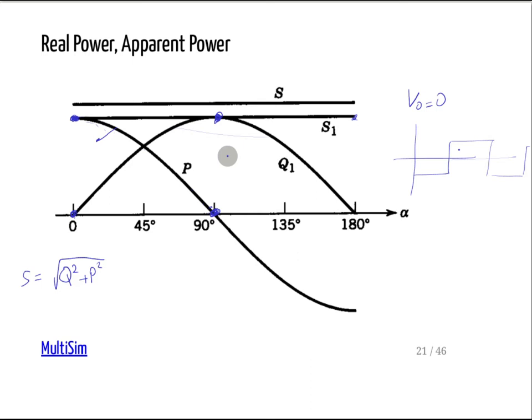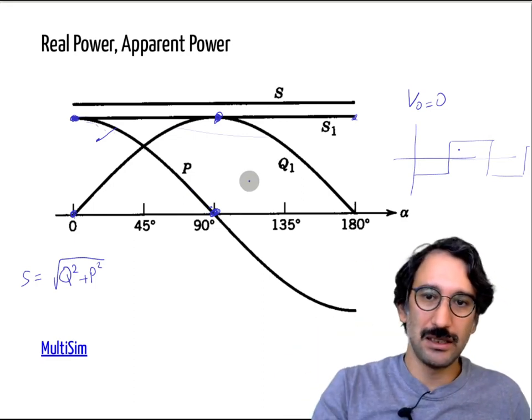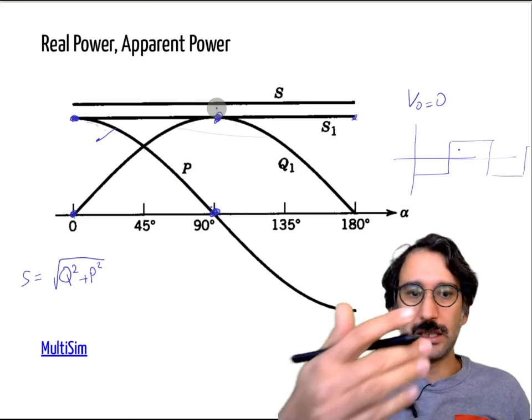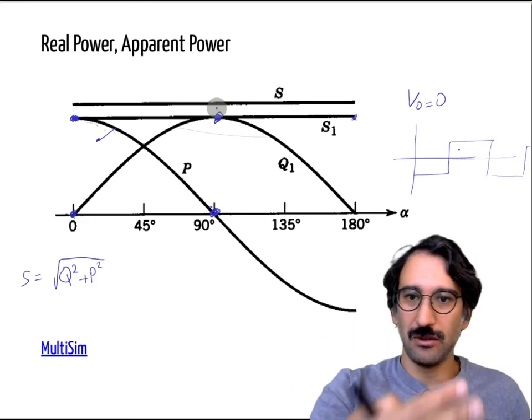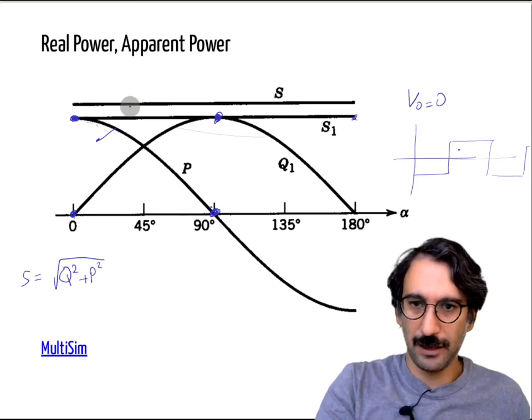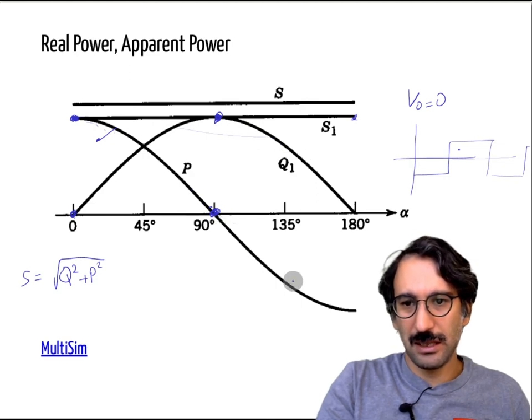So you are just getting energy, then you are giving it back to the grid at that operation. So no real power is transmitted to the load, but it is fluctuating between the converter and the source grid. Okay.